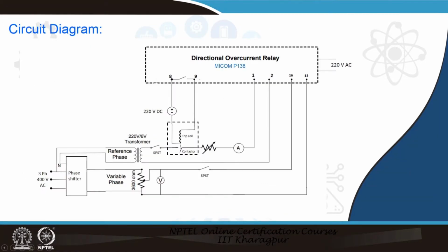When you go for the overcurrent relaying principle, same as what we discussed in the first experiment, if the overcurrent in that circuit goes beyond the setting, the overcurrent relay will operate, and that can be instantaneous, moderately inverse, and a variety of other characteristics, as we have discussed for the overcurrent relay.